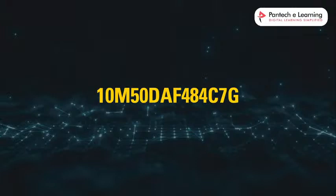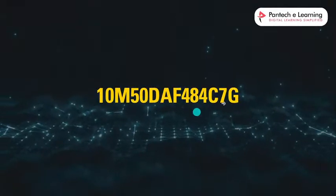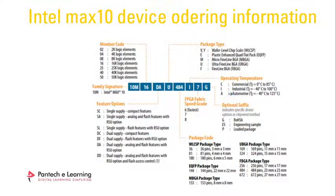And 7 is for speed. Our FPGA board has 7 in the model name, which refers to the FPGA fabric speed grade, like 6, 7. There are various types of speed grades in FPGAs. 7 refers to the speed of the FPGA. And finally, G is the operational suffix of the FPGA.